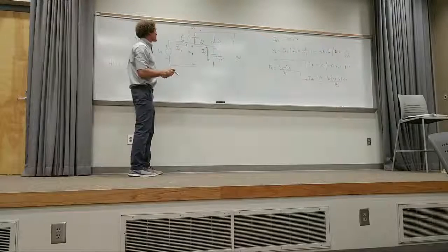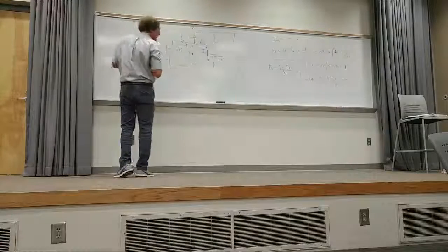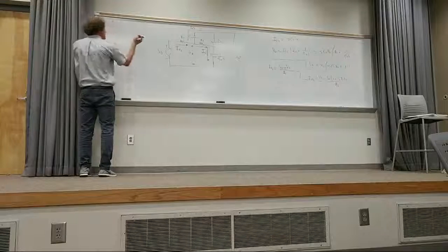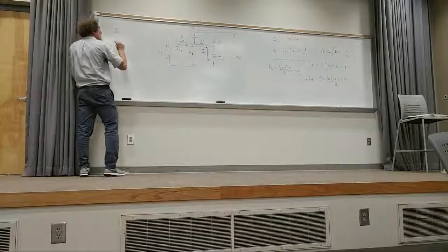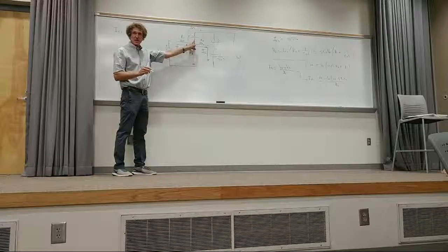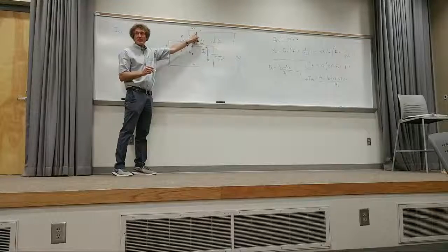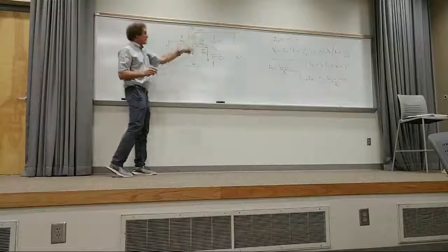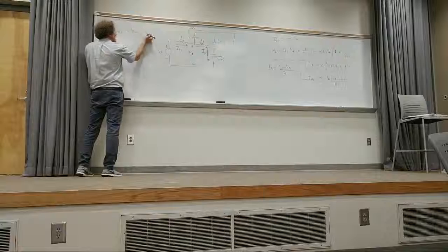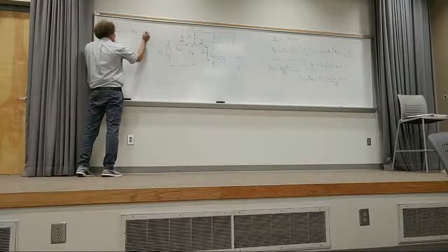All right, so now we have V2 here. What is IC1? Let me put it over here. Just take a look at that. Anyone? IC1, the current flowing this way. What do you always do? Take the voltage at the point the current enters, right? Minus the voltage on the other side of the impedance divided by the impedance, correct? Right? So we have V2 minus what? Class? What's on the other side of that cap? Come on. V out. V out, thank you.